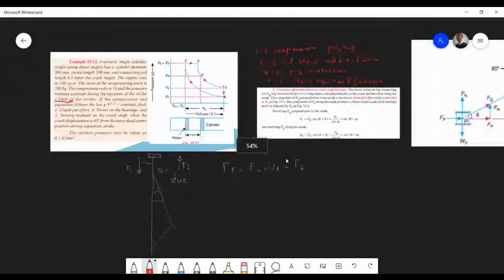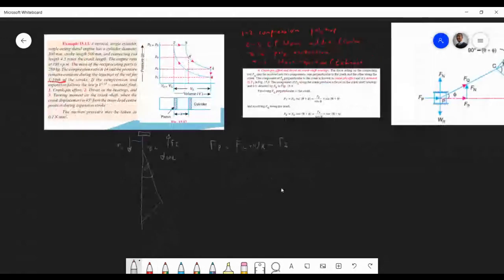Okay, so let's start on the thermodynamics. First, do you remember your laws? When did you last do Thermos 3? I know the other guys have done this. I think Thermos 3 was in 2018. Anyway, we were experts, so we know how to find P2: P1 times the compression ratio to the power 1.35.